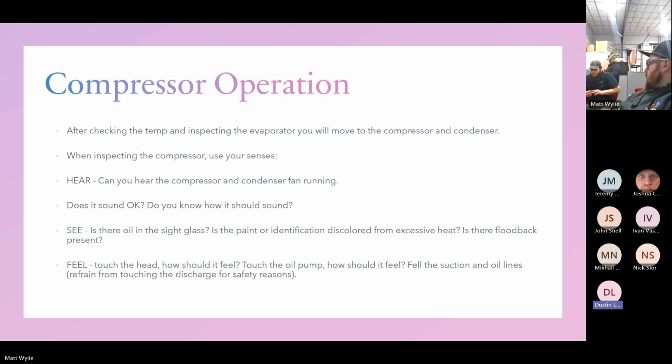Same thing: I ran a call at Jackson's in Reno, and they said their unit was only a year or 2 old, and they said it never worked from day one. It always iced up, and it never did what it was supposed to do. This unit sat up there with the fan running the wrong direction for the first 2 years of its existence. So just keep in mind with 3-phase, if something is running the wrong direction, take one of the legs and swap it with the other.